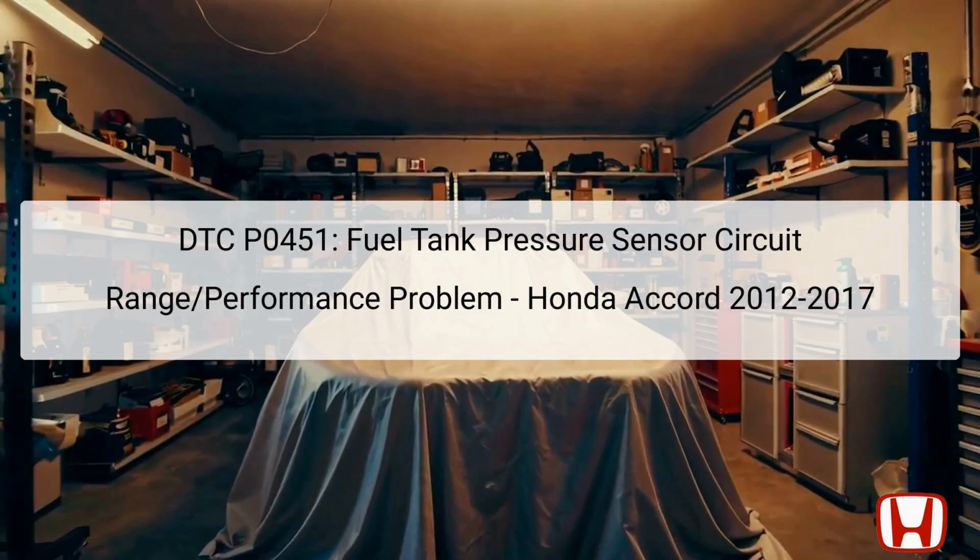However, if there are rapid changes, potentially caused by electrical noise, the Powertrain Control Module (PCM) may consider this abnormal. Such fluctuations, detected over a set time frame, trigger the PCM to store the DTC P0451, which signifies a malfunction in the FTP sensor circuit, and adherence to environmental regulations becomes critical.